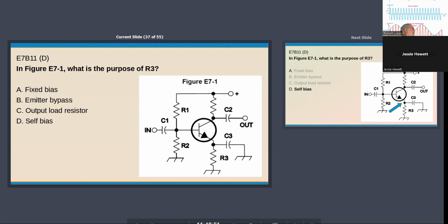What's interesting in a circuit like this with no input, the voltage on the base is just the ratio of R1 to R2 connected to DC. So it's approximately that, because there is a little bit of current. When you first apply voltage, essentially, you can analyze these like at cutoff, the transistor is open, so there's no current flowing through R3, and you're looking at the base to emitter voltage for the bias. So with no input, there is more or less a fixed voltage on the base. It's just the value of the resistors when you apply power. So where do you bias it?